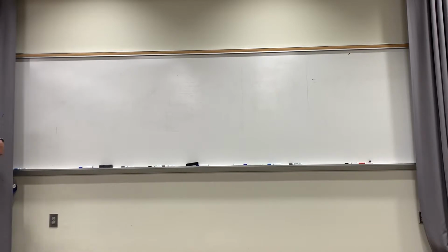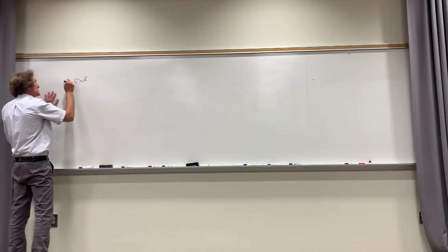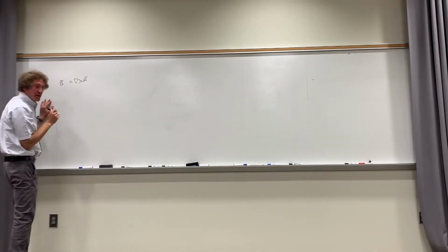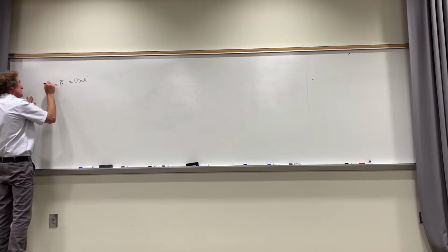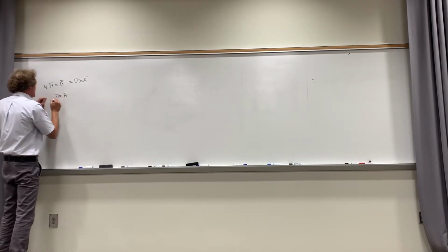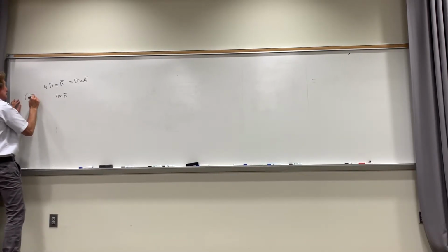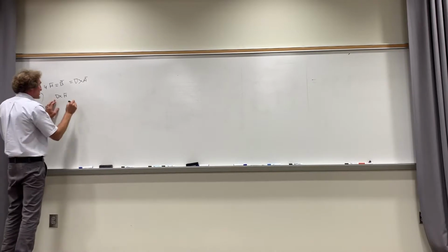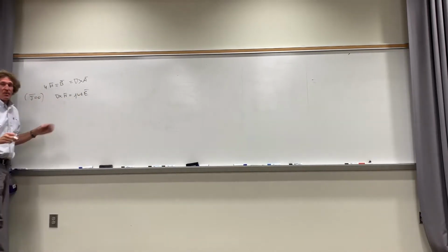Let me restate something. If you have A, the curl of A is equal to B, right? And B is mu H. And the curl of H, if we're a long ways away, where J equals 0, that's no sources, curl of H is equal to j omega epsilon E. And that always works.